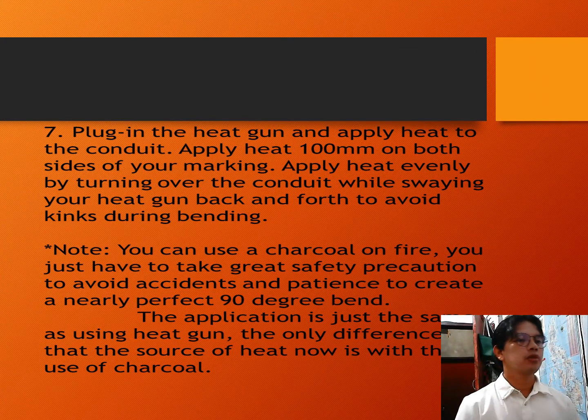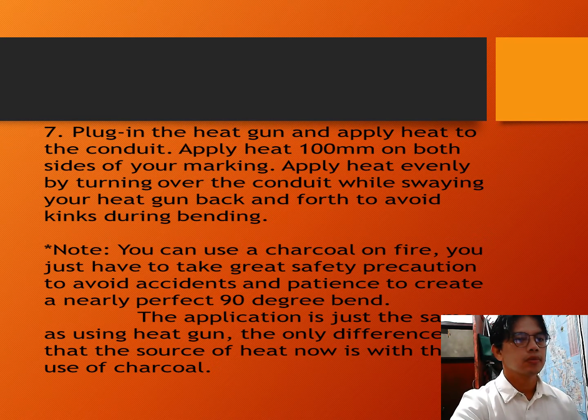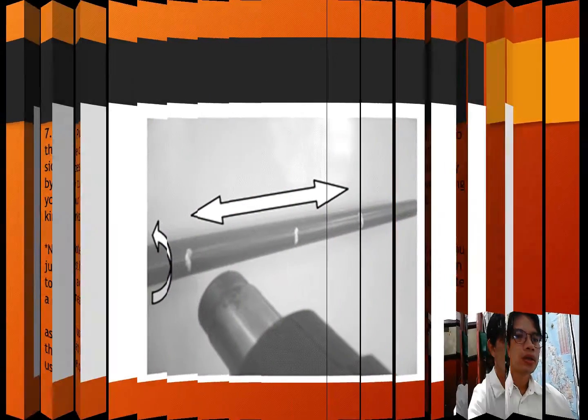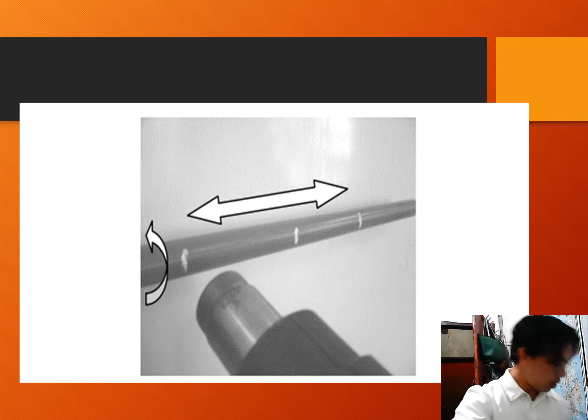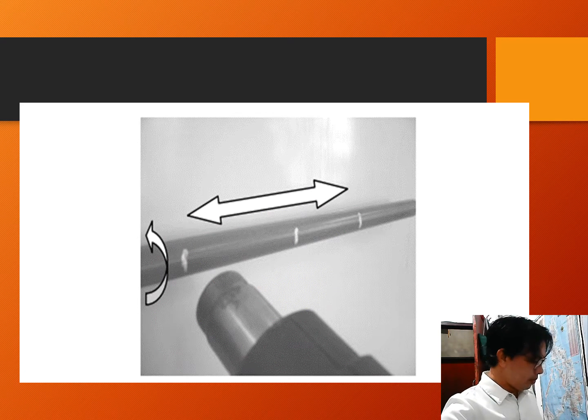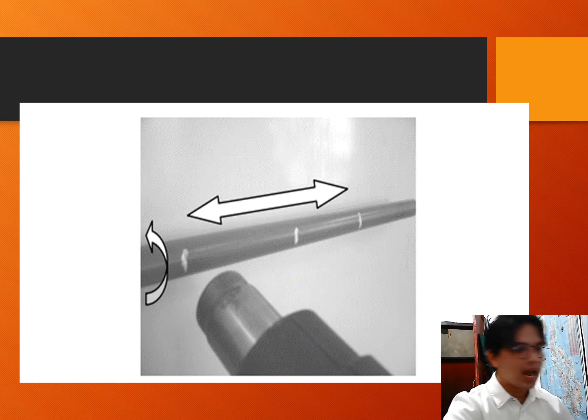You have to use a heat gun if you have one, or if none, use charcoal or butane. In bending, you have to measure from the center, 1 inch.